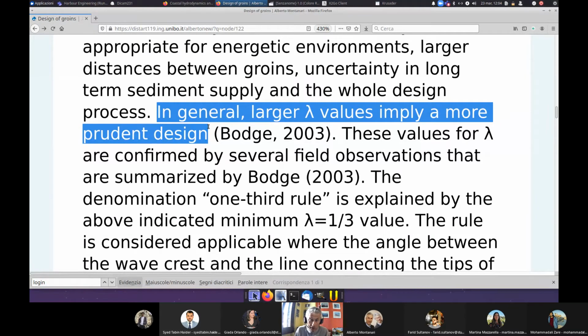Why? Because erosion is more pronounced during winter in our climates, and during summer you usually have quiet conditions. They try to remove the sand during the season when the sand is prone to erosion. So in order not to lose it, they decided during the winter to move the sand landward and to reconstruct a sort of artificial dune. This is extremely interesting. By looking at what people did, you realize that this is an excellent opportunity. If you want to protect the beach, this is a great solution.